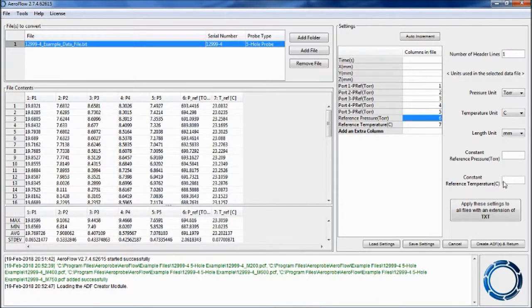The same applies to the reference temperature. Tref is the total air temperature, important for calculating flow velocity from Mach. If the probe being analyzed contains a thermocouple and was provided with a thermocouple calibration from Aeroprobe, AeroFlow will apply the calibration and recovery factor in order to calculate the accurate total and static temperature.